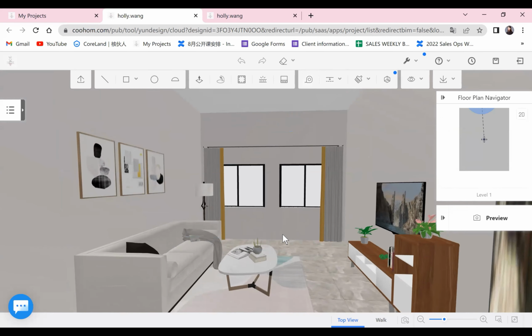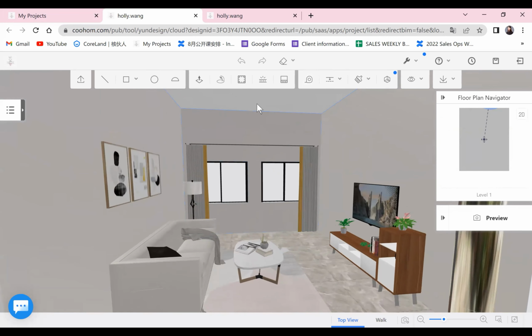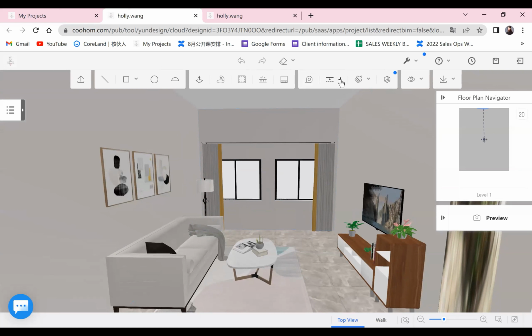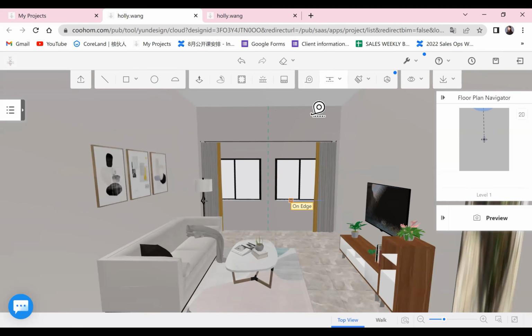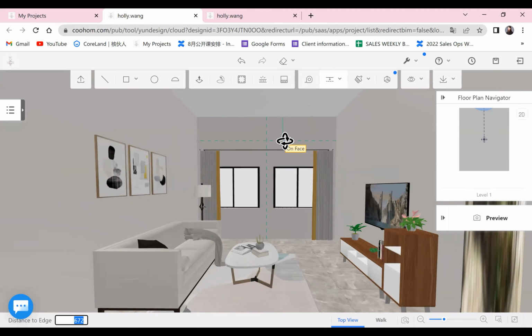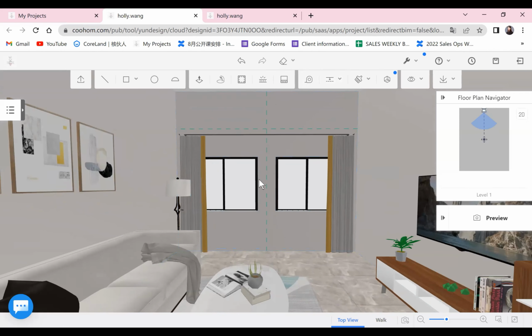That will help you to get the shape done easily. Let's get the middle points and draw the shape like this. So first you add guides at 2,000, that will be the middle. And I want the ceiling to be 800, so another line, 800. Now I have these two lines to help you.